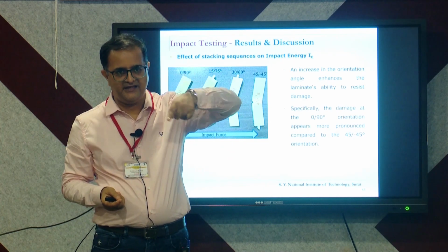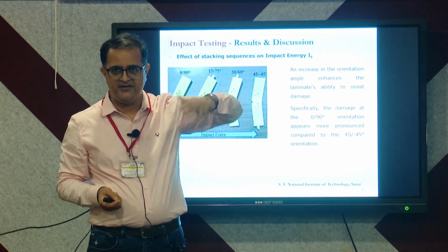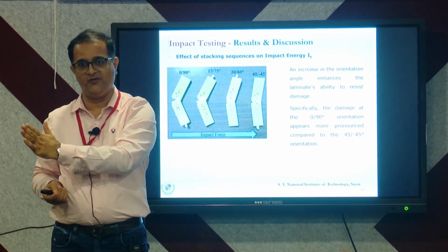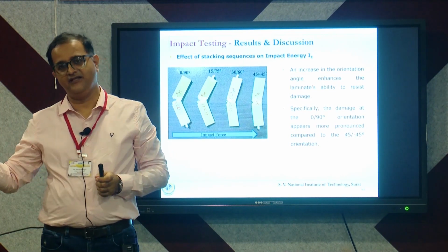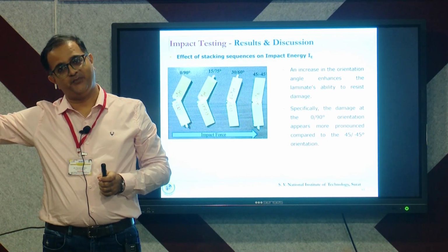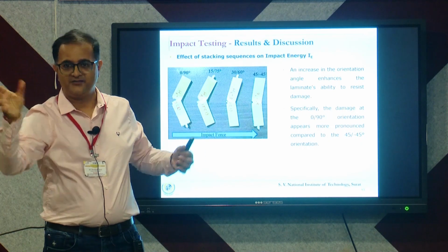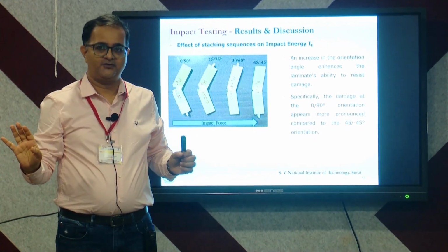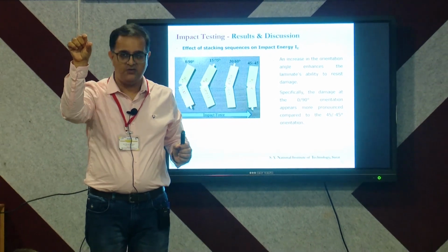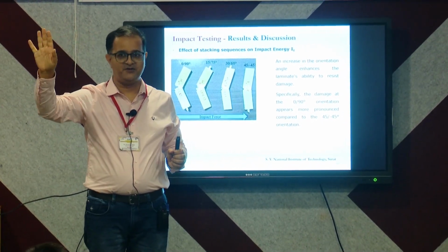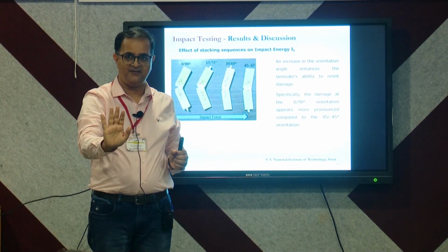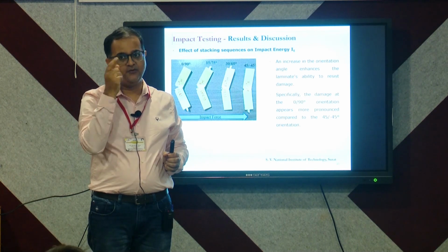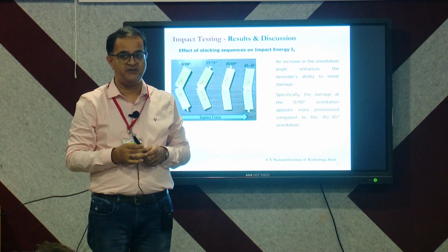It will take a radial path, keep growing that radius and flow, and eventually reach the other corner, and there would be some corners which are left without resin. So if you are making a part from that particular corner, you may leave that part where there is no resin, but nearby also resin infusion is less.